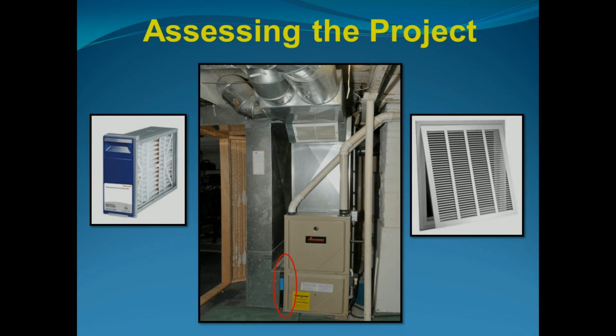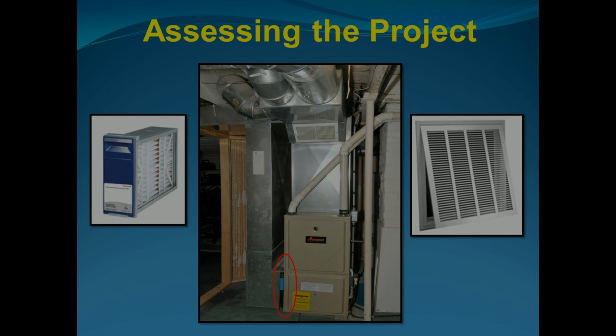If you have media cabinets, they make what they call retrofit models, which are designed specifically for that cabinet. So be sure what that cabinet is. If it's a SpaceGuard 2200, for example, make sure you ask for the 1-inch panel that fits. It's the retrofit model that fits the SpaceGuard 2200 or 2400, whatever it is. But it'll be designed to fit perfectly within that media cabinet so that it's not flopping around, there's no blow-by. It's essentially the same air cleaner, it just has a track system built on the top and the bottom of it. So you have retrofit models, and as Steve already mentioned, you also have your 1-inch filter back return grills.